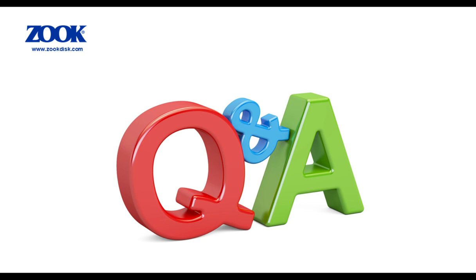Okay, thanks, Scott. Rick here. Good question. So a fail-safe disk is designed to burst at its rating or even lower if there's some kind of issue with the installation. So what kind of issues could those be? Well, it might be damage to the disk. It might be the disk fitted with the incorrect orientation, so somebody fits it upside down, that kind of scenario. And in those scenarios, a fail-safe disk will burst low.